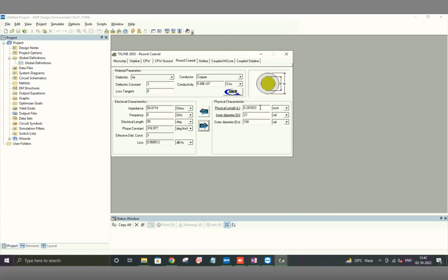Disclaimer here is that these calculations are always somewhat approximate. You will find that when you actually make these things, there are always tolerance issues and other things which will give rise to some small variations, usually of a few percent in what we make here. Usually what we do is we start with this to get an estimate of the dimensions we need. And then we do a full electromagnetic simulation to confirm that it is as close as possible to the properties we want. And then we do tweaks for that. But it's a good starting point.